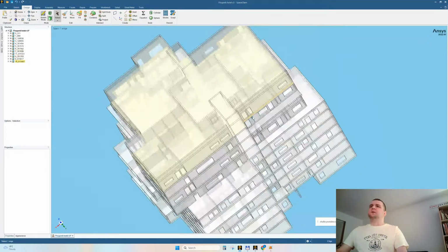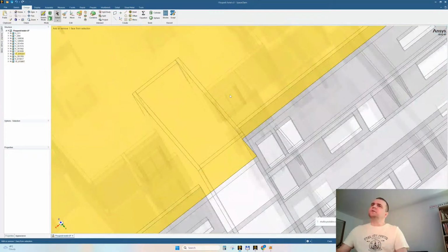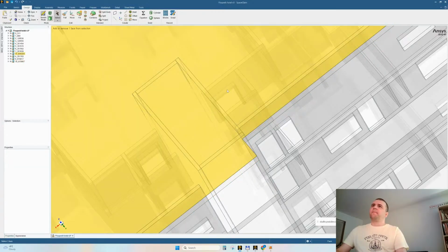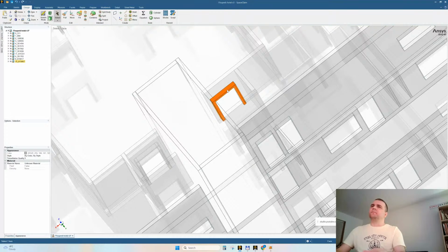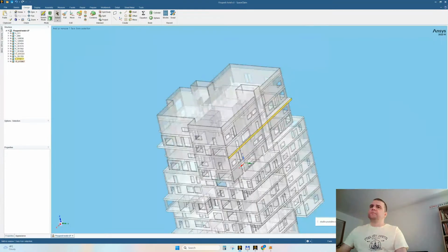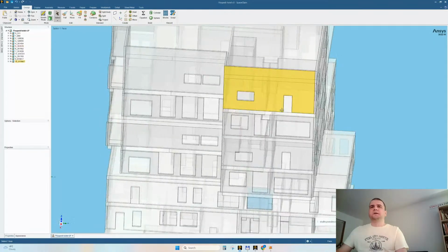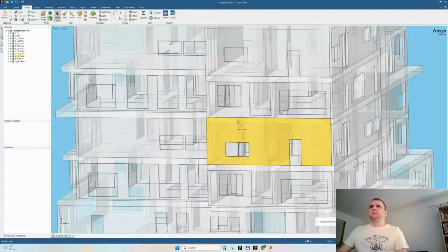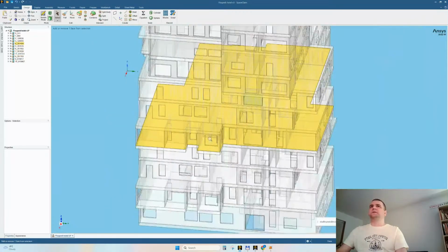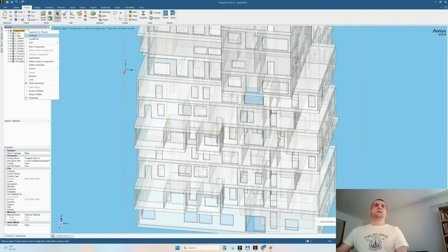Let's not overkill it. We have a door. I thought I removed all the doors. This is a door frame. All right. I'm looking at frames. I removed also the stairs because we want to quickly obtain results. Right-click, delete empty components. Right-click, source, internalize all, and save.